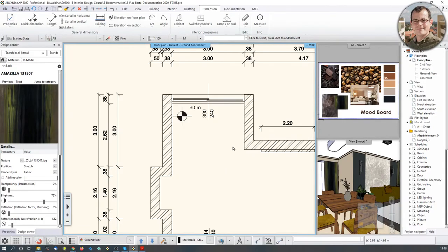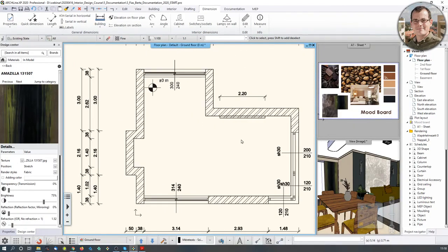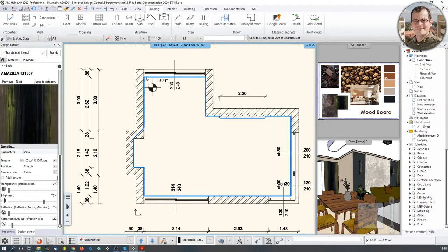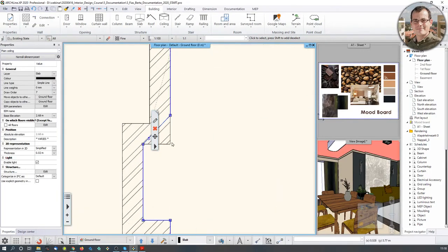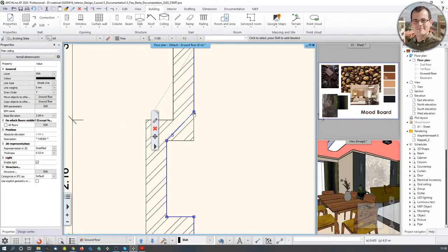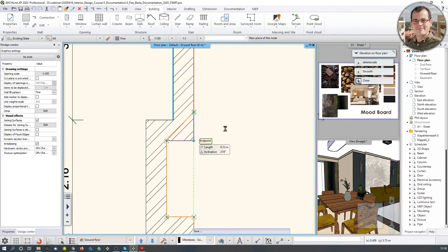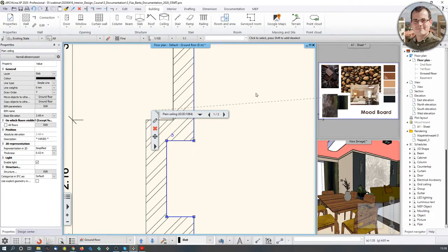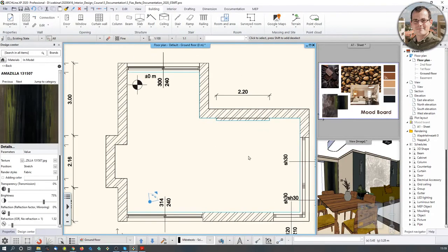So let's start with another. What should be next? I think the room and area stamp would be the next two-dimensional group that we are placing. Now, when it comes to rooms, the software is able to calculate elements which are highlighted or bound by walls. By the way, if I hover my mouse here, you see a very strange sketching problem that I did. The ceiling was made a bit hastily, so this point is not good. If I click on this move node, I can fix that. So that's just a quick detour, so as we are not leaving anything unsaid.